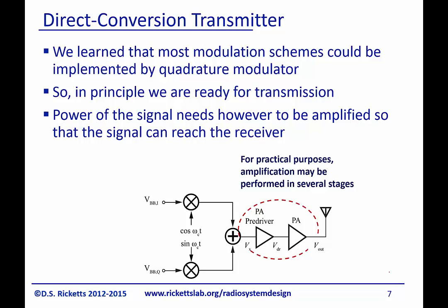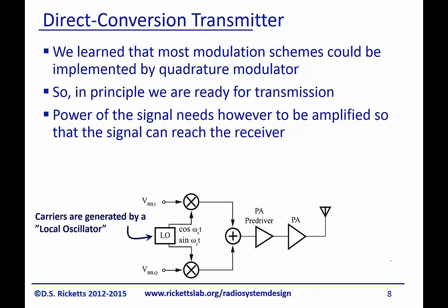Now practically, typically we're not going to have a single amplifier. We usually have a cascaded stage of several amplifiers. And that's just because, like I said before, typically our goal is for very high output power here at the end, and each amplifier itself may not have sufficient gain, so we just put in some preamplifiers to take care of that.